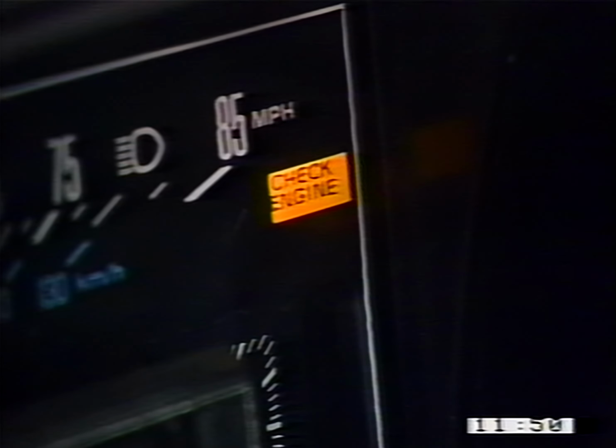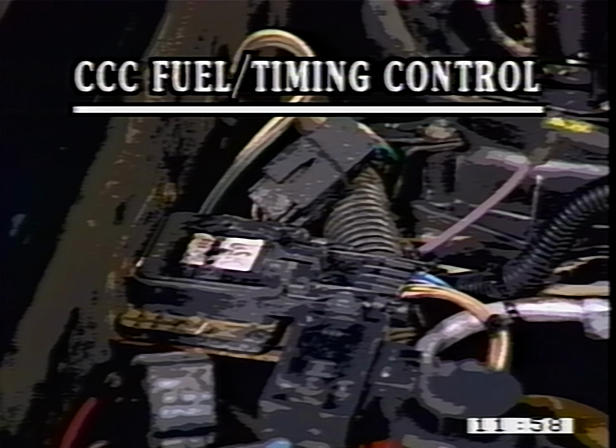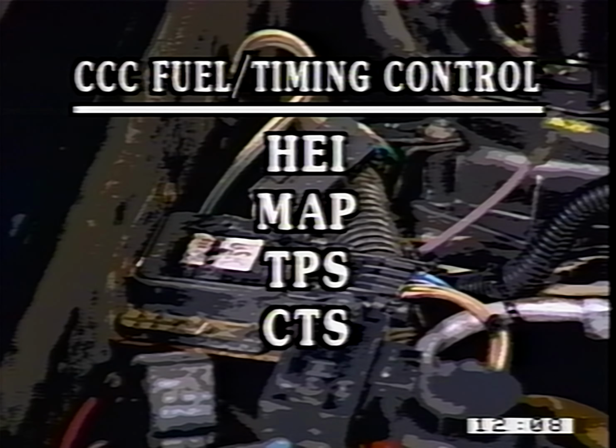Now let's take a closer look at the C3 system's components. The C3 systems depend on 5 primary signals to determine the necessary control of fuel and timing. They are the HEI reference, manifold absolute pressure sensor, throttle position sensor, coolant temperature sensor, and the exhaust oxygen sensor signals.